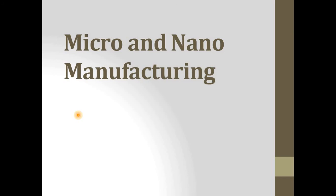Today we are going to discuss micro and nano manufacturing. So in nano micro machining process, the actual material removal can be limited to the surface of the workpiece, that is only a few atoms or layers of atoms. At this range, inherent measurement problems and the lack of more detailed experimental data limit the possibility of developing analytical and empirical models, as more assumptions have to be made.